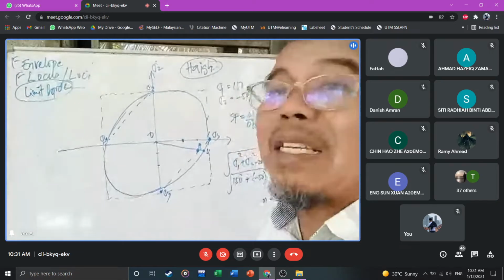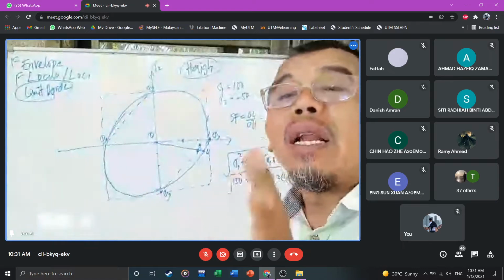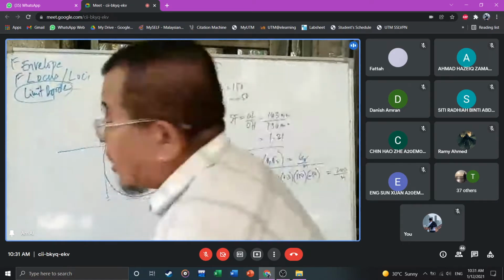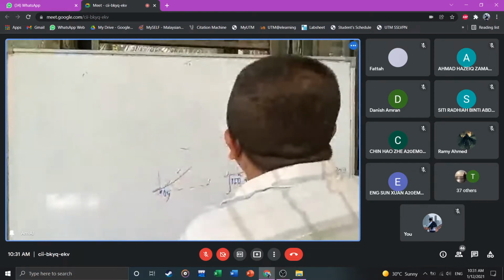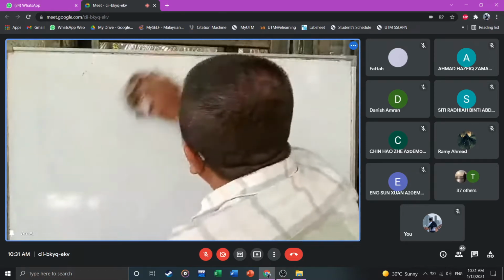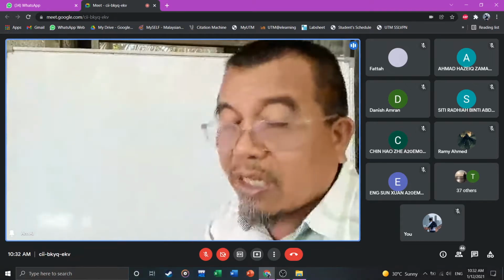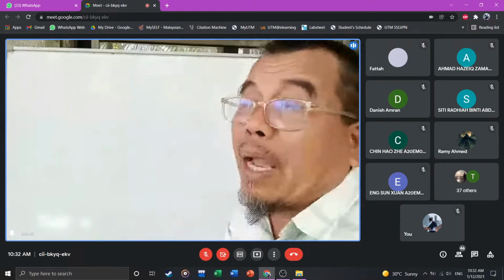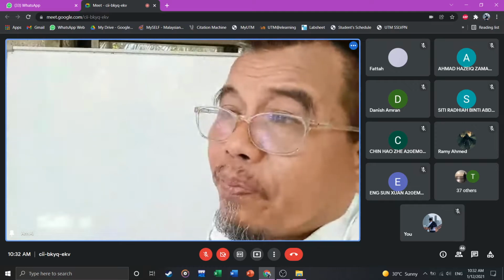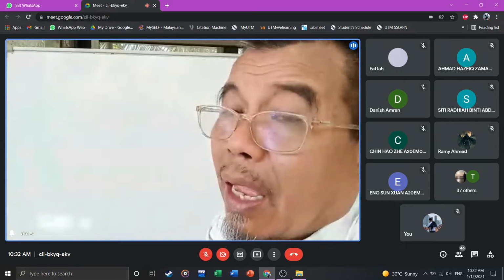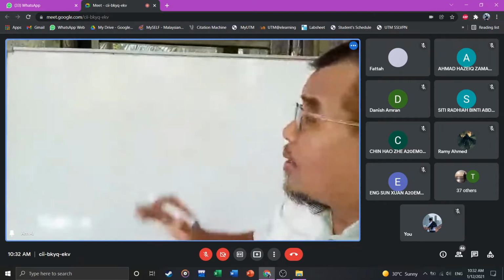Let us do some exercise, a reverse question. We have done the reverse question on the first day. Let us do that for this failure theory. Okay, we can do this exercise as homework later on. What are the reverse questions? But we do it by the Mohr circle. We have to do the Mohr circle. We have to find sigma 1, sigma 2, sigma 3, and we have to set a safety factor. Okay. Look at this.